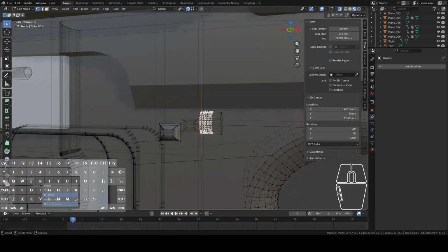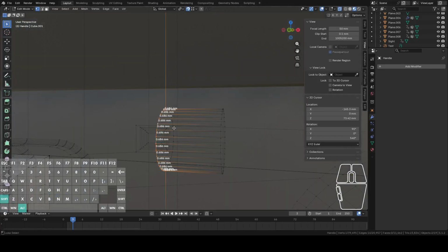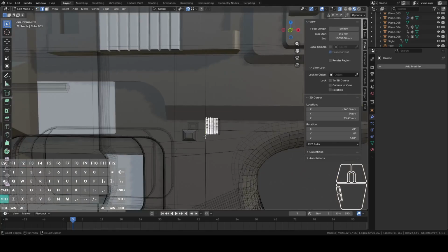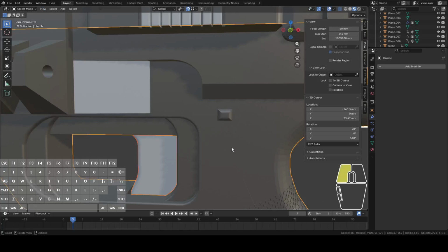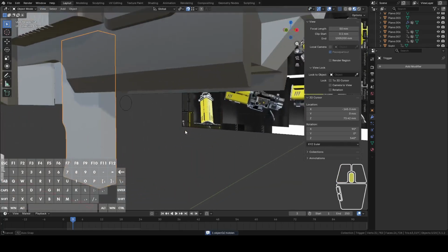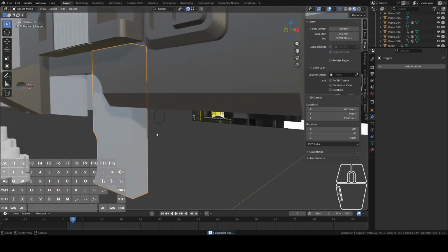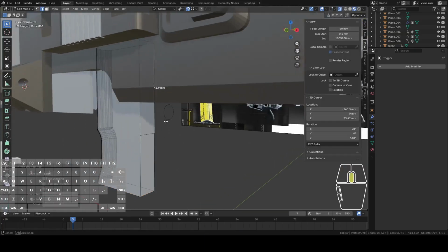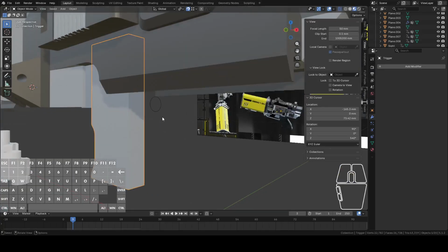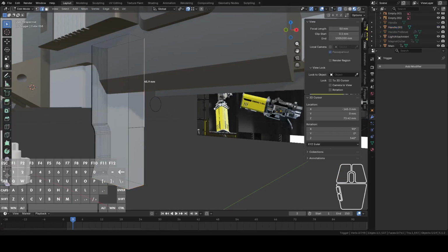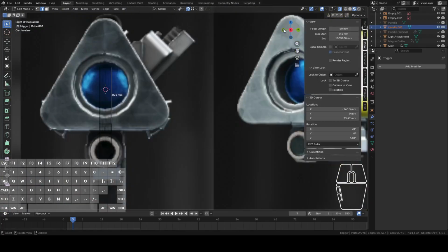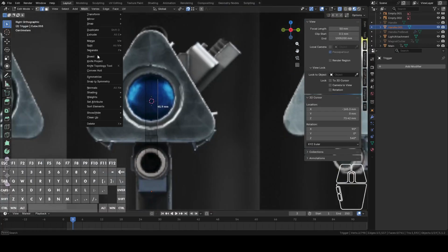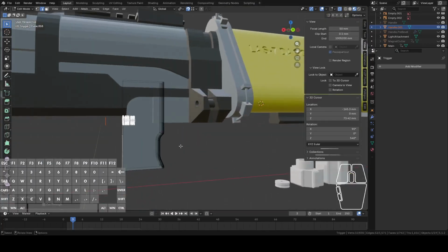So to do that, I'm going to take this edge loop here, which is the size for our spring. I'm going to Shift D and then P, separate selection, and then I'm going to hide this. And with that, we can put the dimple right in the back of here with edit, and then control. Okay, let's find out what we got there. Handle point 1, okay. With that, edit, let's go over here, control, left click, and then with the rear orientation, we'll go to mesh, knife project, and stick that in there.